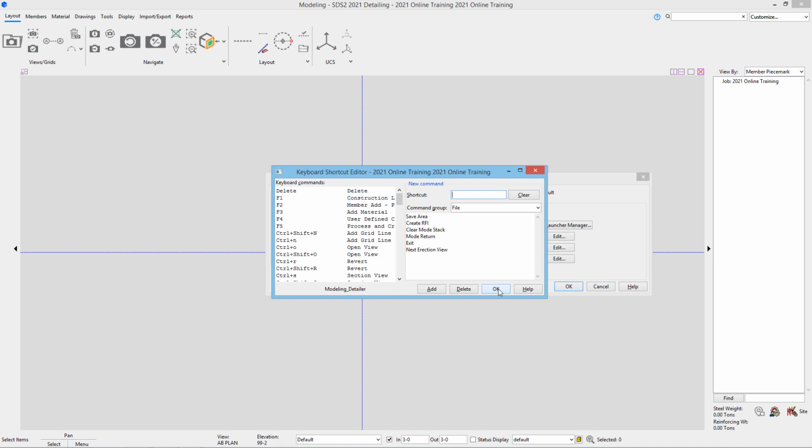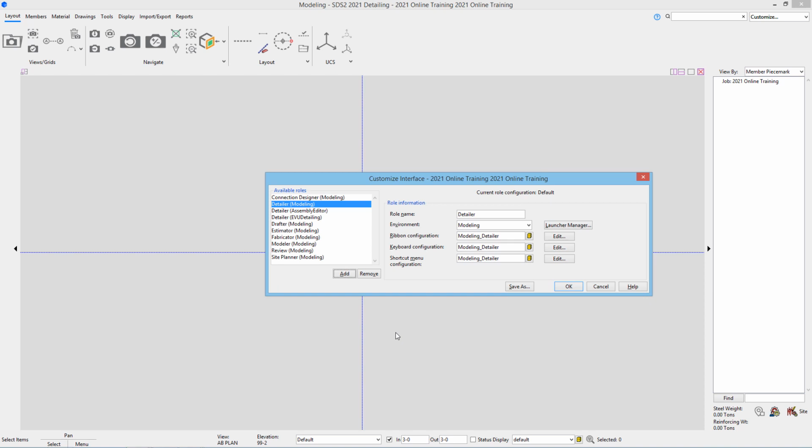For this training, I have created a document that will list our keyboard shortcuts that can be accessed in our additional references section for both modeling as well as drawing editor. When we are creating our shortcuts there, if the shortcut already exists, you must delete it first and then you can reuse those key combinations. You can have multiple key combinations work for the same tool.